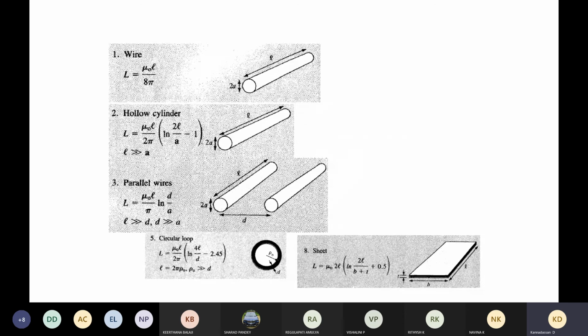And the interesting part is, if you take a small wire, when a current flows, it will itself produce the magnetic field. Obviously, by increasing or decreasing the length, self linkage could be possible. Once you have calculated this self linkage, you just divide by the current, and you will get the inductance. So that kind of inductance is possible for a simple wire itself. They are called wire inductors. And if you make it a helical shape, then spiral inductors will come.